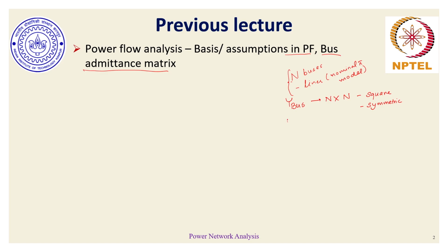We also saw another crucial aspect while evaluating Y bus. Z bus, which is also known as the bus impedance matrix and also turns out to be an n cross n matrix for an n bus network, is nothing but the inverse of Y bus. It is difficult to find this inverse in order to find Z bus if there is no proper connection to ground or neutral point through which the bus voltages are being measured. So the governing equation is that Y bus correlates all bus currents as a function of all bus voltages.